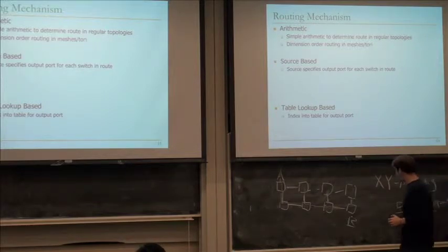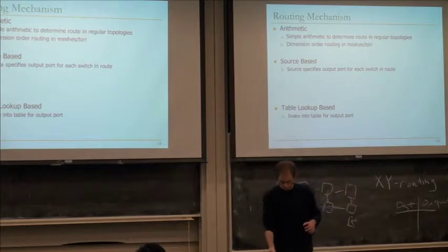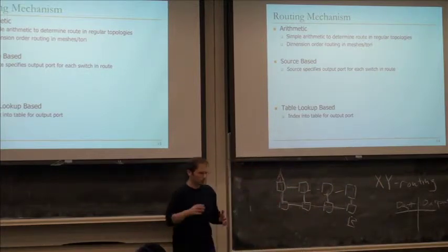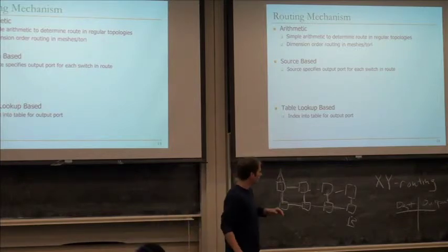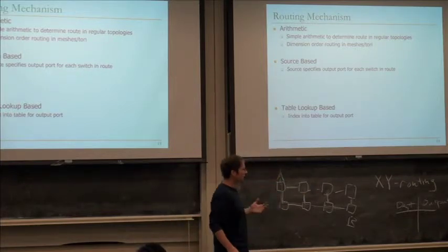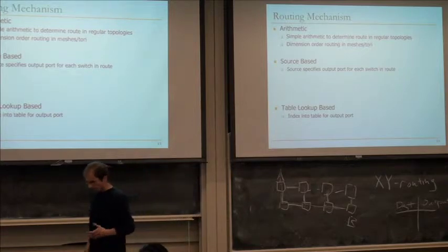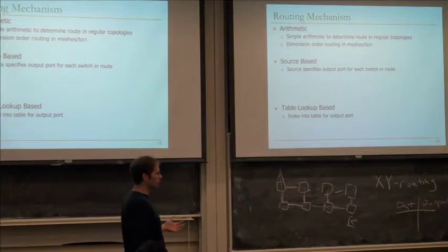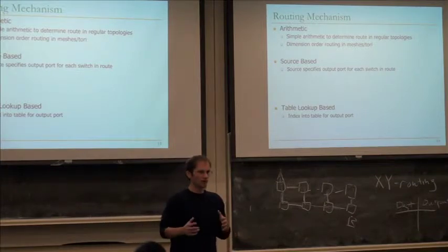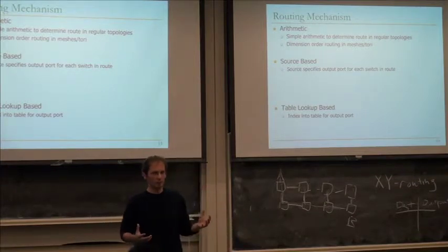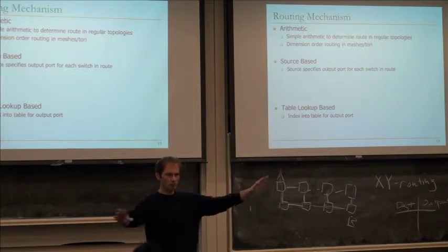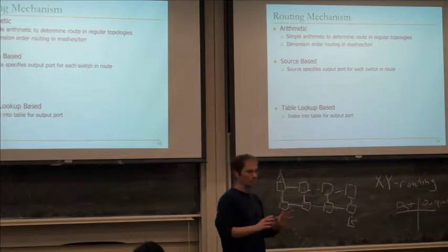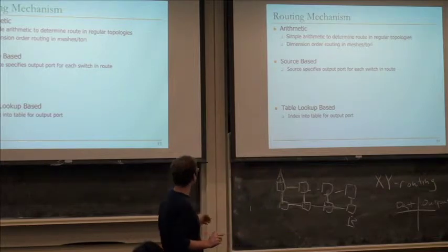And you can imagine ways to build this efficiently in hardware. Maybe you have a CAM that is prefix matching based. Maybe you have just an all-possible-combinations table. But the basic idea is that you have a table, and that way it's more flexible. That gives some other advantages as well. If you use tables, you can do things like dynamic reconfiguration, where you could say, based on the congestion that I see in the network, every n cycles I'm going to reconfigure my whole network and try to shift traffic away from congested regions, or rebalance routes or something like that. So that can be nice.